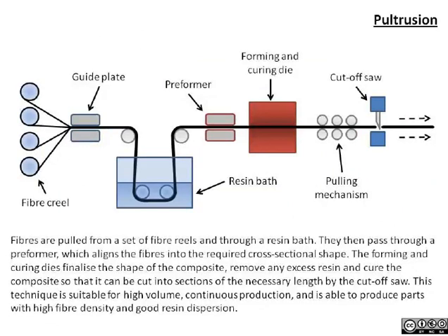If instead of pulling a fiber and winding it, we pull it through a resin bath and then cure it in any given shape, this is a process called pultrusion. It's effectively similar to filament winding, except it's more axisymmetric. Typically, the fibers are cured in a straight configuration rather than winding around something, but otherwise has the same idea, that we're starting with something flexible, one or more fibers. We can blend those together, have different types of fibers, but the key is to have them go through a thermoset resin bath in its liquid, non-cured form, and that gives us our matrix.